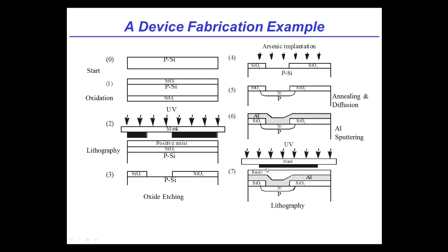So all we're going to do is do another lithography step. Here we've got resist and a mask through which we're going to apply UV. Okay? So want to take it from there? Sure. So because we used that mask, we were able to get photoresist in the regions we wanted. We can then etch the metal, just like we etched the SiO2 earlier. And so what we're left with is a patterned metal. So in other words, we're now able to make a contact to the device right where we need it.